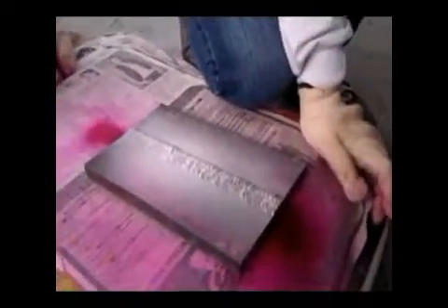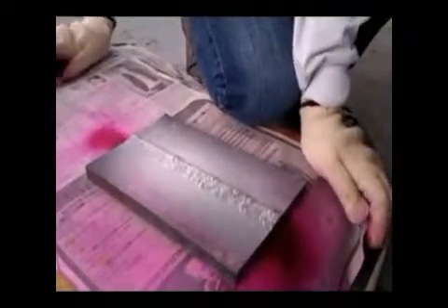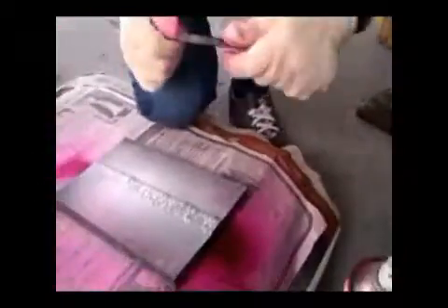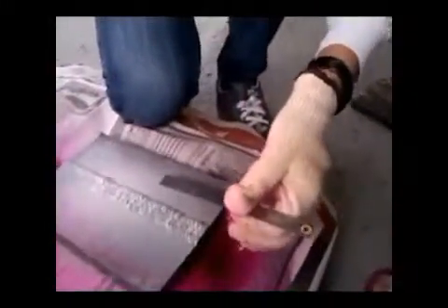Inspection of the test surface should take place after a 10 to 30 minute development time, and is dependent on the penetrant and developer used. This time delay allows the blotting action to occur. The inspector may observe the sample for indication formation when using visible dye. It is also good practice to observe indications as they form, because the characteristics of the bleed out are a significant part of interpretation and characterization of flaws.